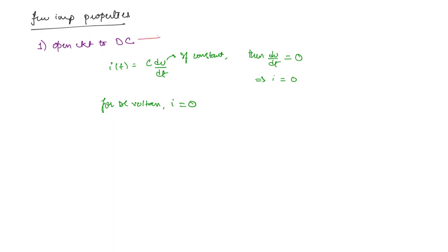But one important point to know here, this is true only in steady state condition. So, there are two conditions, transient and steady state. Steady state is the one which will remain after the transient will pass, right. So, we will discuss more about transients later, but for now you just remember that at steady state the capacitor will act like an open circuit to the DC voltage.